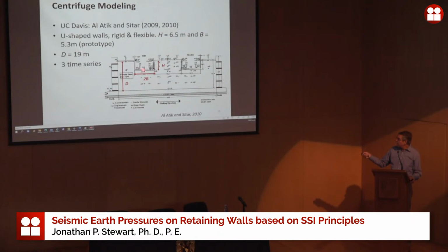And then the key detail of these tests is there's distance between the bottom of the U and the bottom of the model. That's important because this soil here allows the wall to translate if it wants to, it can rock, it can respond in a natural way. That's important to point out because a lot of the theoretical solutions we have, and many of the past experiments also, are on a rigid base. So on a rigid base, the wall can't really move that much. In fact, it can't move at all at its foundation. This is a more realistic setup, so that's a very nice feature of these tests.